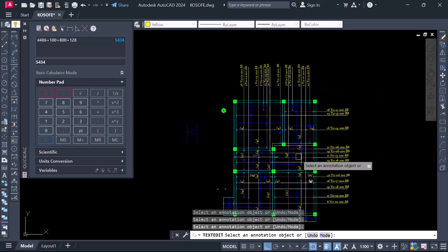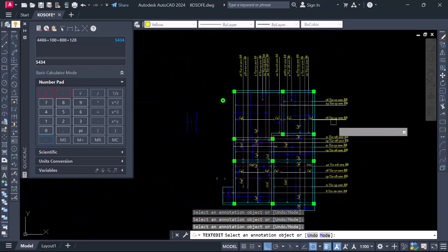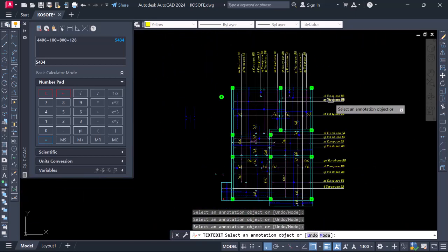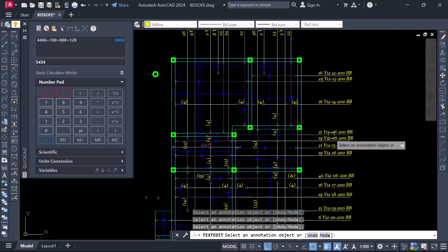You can decide to run some top reinforcement as a top runner. You can still take it to be 10 mm. That would be good, a 10 mm size reinforcement, depending on what you're doing. But for the purpose of this video, I want to keep it simple. I want to make it 12 mm reinforcement.